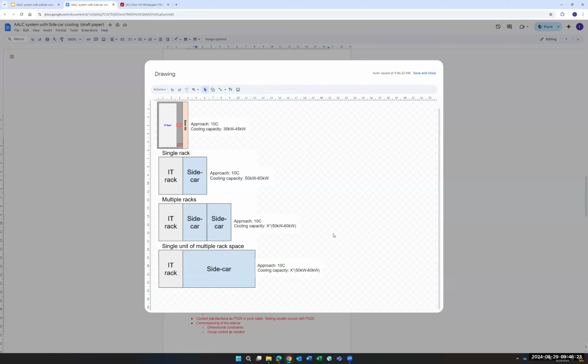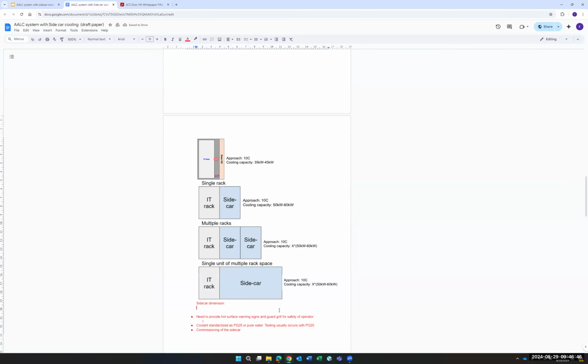Yeah. Now, if the bottom one were 2 cabinets wide, the bottom one would probably have a cooling capacity that is more than twice what a single wide is, just because of the design efficiencies that you'd get with a single large heat exchanger versus 2 smaller ones. Yes, it could be. Yes, the efficiency is higher. That's why there could be maybe 10% more cooling capacity that way. So maybe instead of showing the bottom one being almost 3 cabinets wide, you make the bottom one 2 cabinets wide.